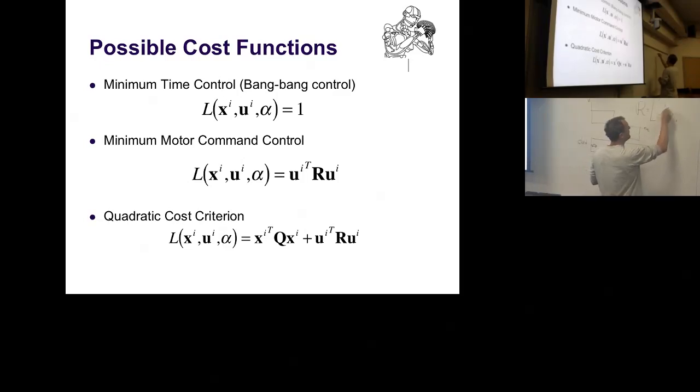That's super simple, like this. But you could also say, let's make this my arm which is moving. And I say, okay, if I move my shoulder, that costs me a lot because I have to move a lot of inertia. So how about I put a big weight on that? So the shoulder is degree number 1. I make this 100, and say my elbow costs me only 10. Moving the wrist is totally cheap. Moving the fingers is very cheap, and moving the last segment of my pinky costs me almost nothing. So that's actually a useful way of weighting things.